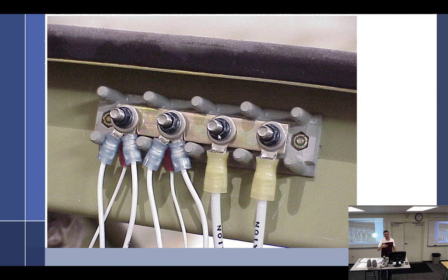You just don't stack stuff up like that in aircraft. For nav lights, there's 3, and that's fine. One switch operates 3 lights, and that would be normal. So you can put 3 ends on one with the power coming in and 3 on the other. But I've never seen a need to go more than 4. And if you do, it's something like this, because now you're getting into bigger loads.